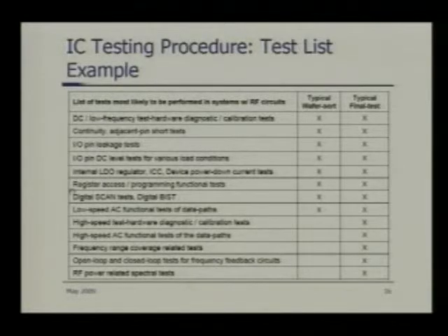Then, if your device is programmable, you have to test for register access, meaning you have to write the values and read back. These are fairly straightforward things. Then digital scan, digital based, etc. But I'm not going to read out everything. What we'll be concentrating on is these last three sections.